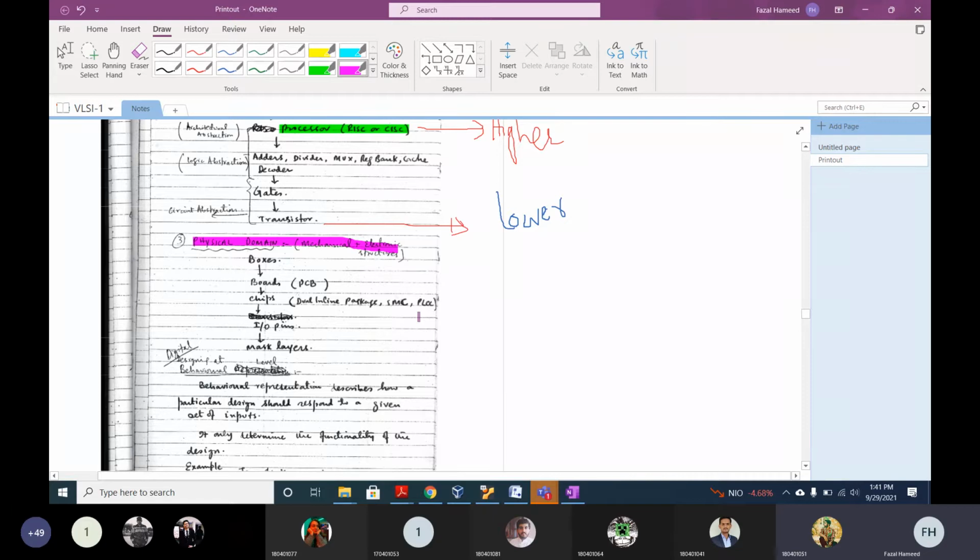And if you look at each individual chip, each chip has some I/O pins. And if you look at each individual chip internally, this chip consists of various mask layers. In each of the chips, we have some transistor layer and we have some metallization layer. When you want to connect different transistors, the transistors are connected through the metal layer. So it's just like a multi-story building.